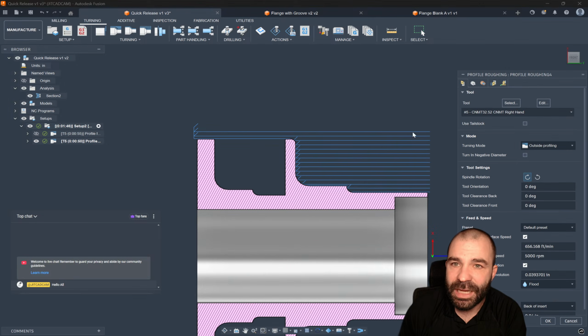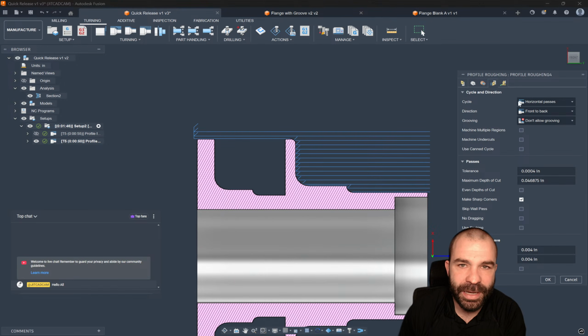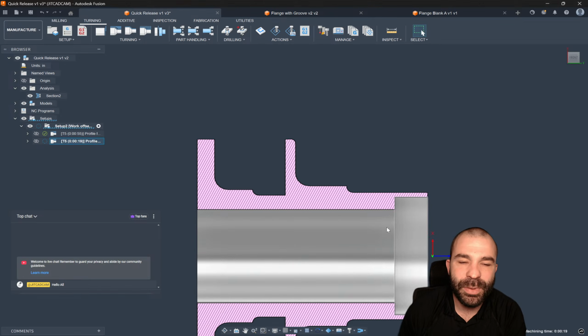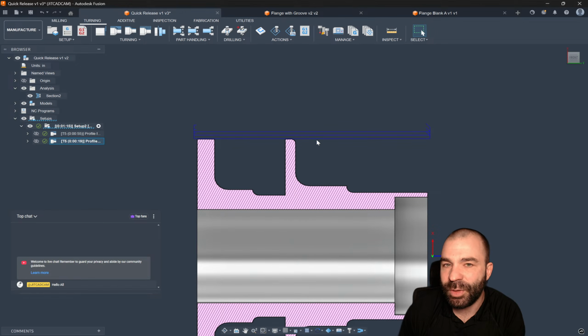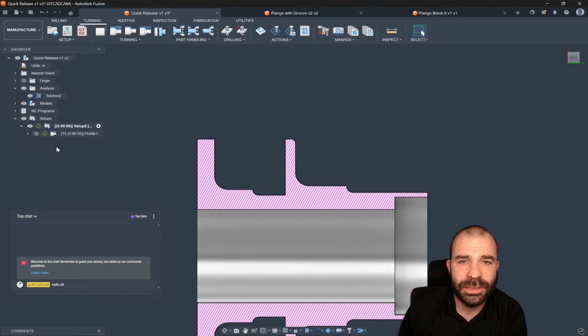However, if you were to change directions in our passes tab, so again, instead of going front to back, I went back to front, because that tool cannot feed back in the X direction, and that's basically what radial grooving is, I cannot go in on X. Once I start in X, I can only feed out in X. So back dragging this part or using kind of a lollipop cutter or a dog bone, I wouldn't be able to plunge back in here in the front. Again, this is why we always say start as early as possible in these tabs. Use rule number 1 to your advantage.